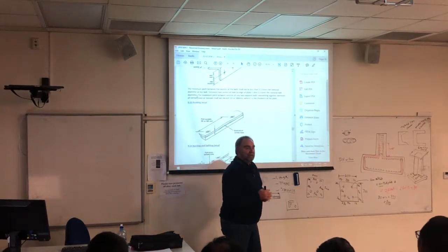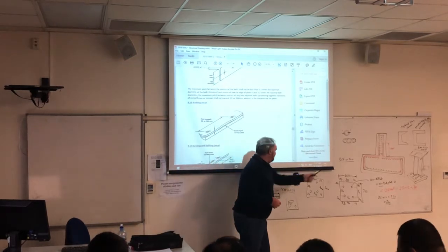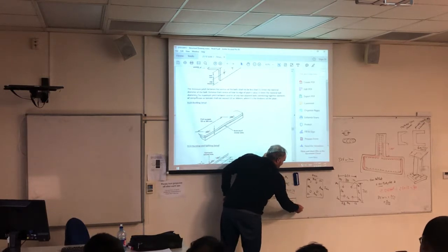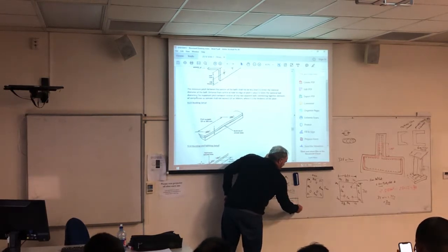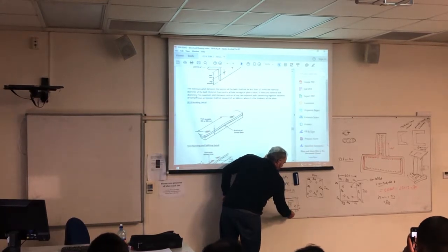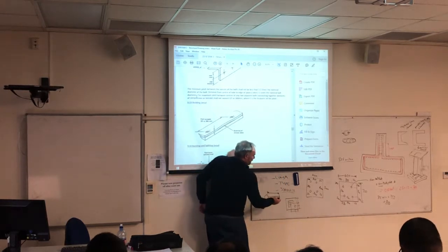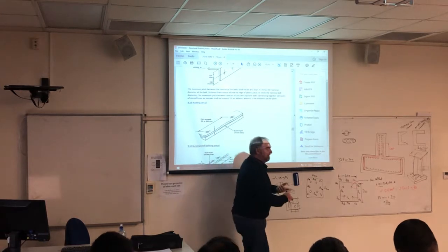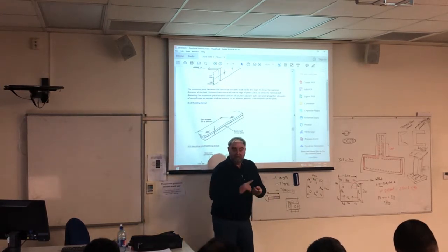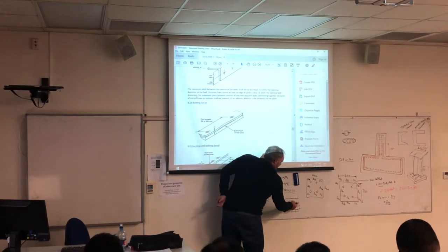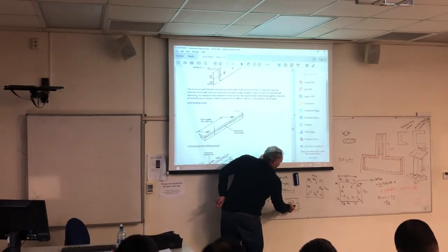And that's for assignment 4. So looking at that in detail, you'll be doing a little plan view like that. You'll have your dimensions to the holes, and maybe to that hole as well. And you'll also have a call up, so you would have to name the bolt that's going in there. You need to know the bolt hole size, and also you need to show the weld.